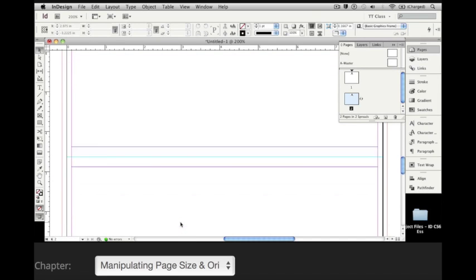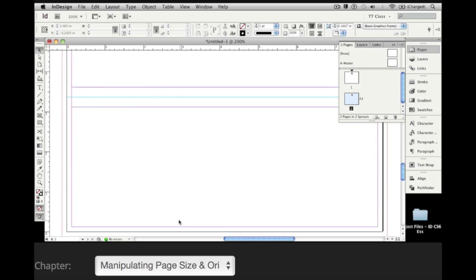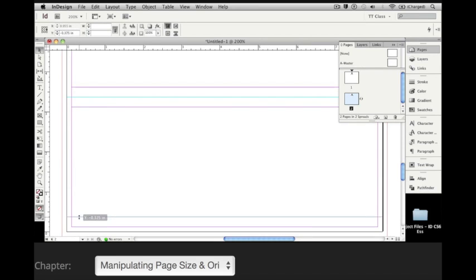And I'm going to go down here to the bottom panel, and I'm going to set this up so that I've got, in this case, a horizontal ruler guide. So I'm going to go to the horizontal ruler, and I'm going to bring that in to the point where that shows. I want to make that 1875, and you'll notice I can't hit that precisely with this ruler. So what I'm going to do is take that in. I'm going to click to select the guide.